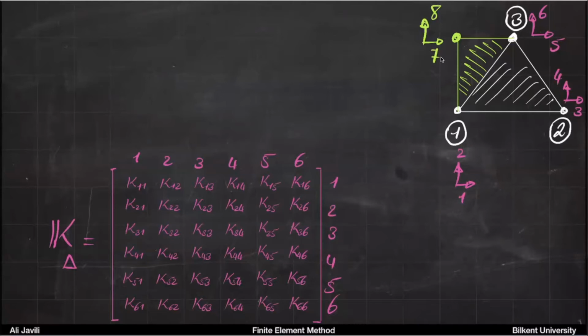So now, also for this triangle, you can write its stiffness. The stiffness of that, it's also a 6 by 6 matrix. So the degrees would be 1, 2. Let's imagine that here you went in a counterclockwise. So this was 1, 2, 3, 4, 5, 6.